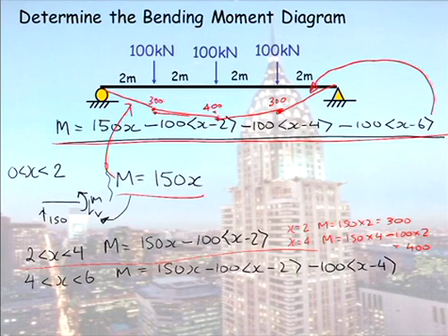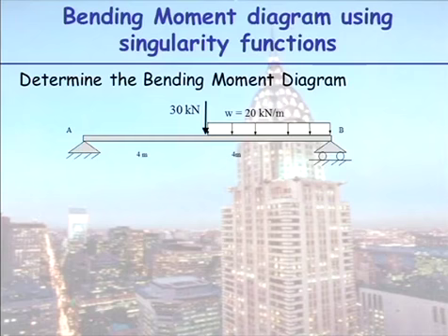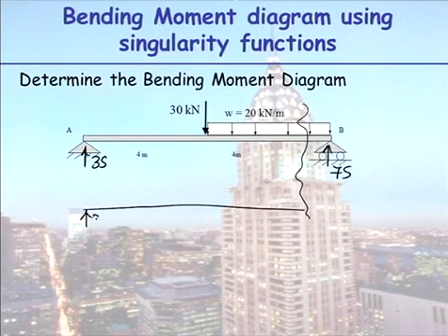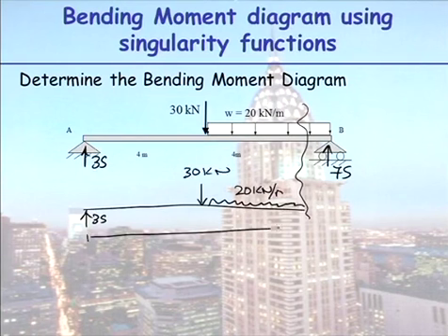Shall I show you something, or do you want to have a go at coming up with one more equation? We've done the shear force diagram for this already. Now I will give you time and everyone have a go. You are going to cut the beam as far right as possible. So you are going to come up with your general expression for your bending moment diagram, cutting it at distance x. I want a general expression for that moment.